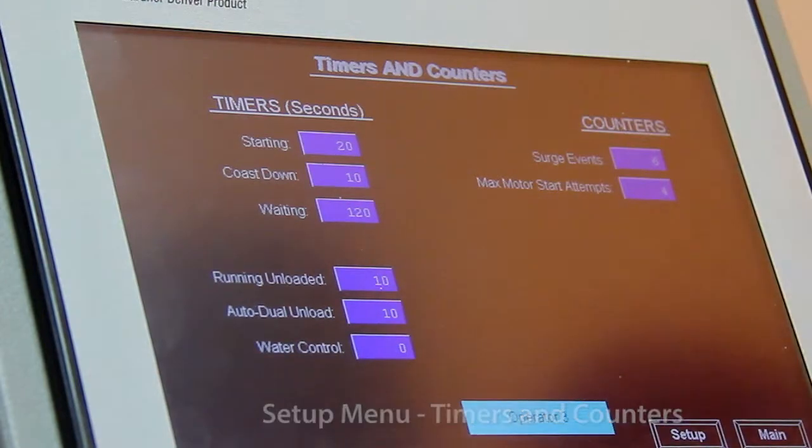So if you have an aux oil pump on your machine that allows the machine to come up, and then you have a mechanical main pump or maybe an electrical main pump that comes in to run the machine, we will shut that aux pump off after 20 seconds, and then your machine will be running on its full pressure pump or the main pump at that time.